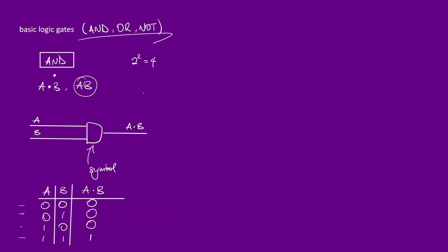All right, we'll see a lot of this as we go on. The second one is simpler, sort of, but it's more permissive. It's not as strict as the AND gate, and we call this the OR gate. What's the symbol for this? You symbolize this with a plus sign. So it's sort of addition, A or B. If I wanted to show the OR expression between 2 variables, I'll simply write A plus B, or X plus Y, and so on and so forth.